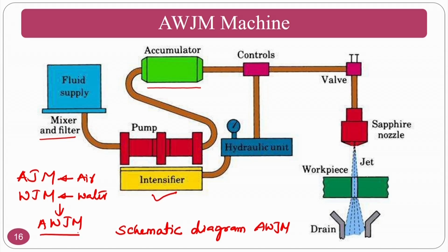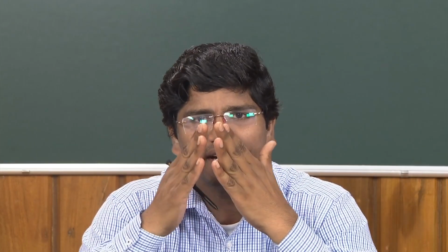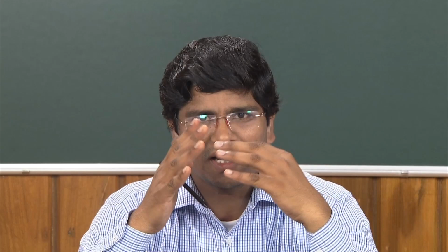The advantage of abrasive jet machining is that you have the abrasives, you can cut, but the only problem with abrasive jet machining is that divergence will be there, so stray cutting will be there. In order to counter it, on the other side there is water jet machining, where the capability of water to cut is very less. However, the coherent nature of water is there. So, if you can combine both, what will happen?